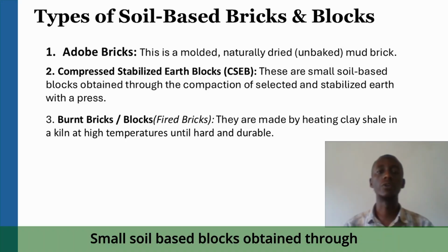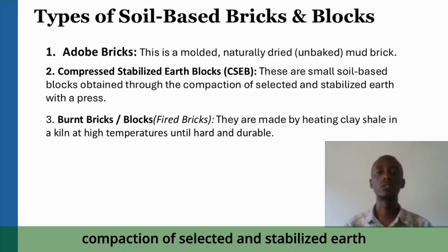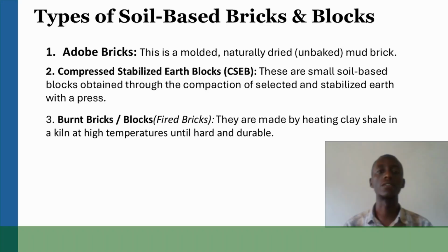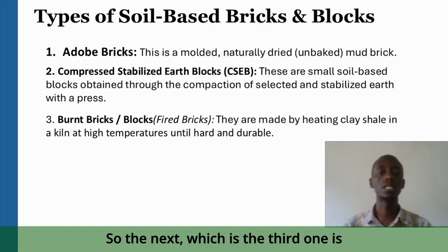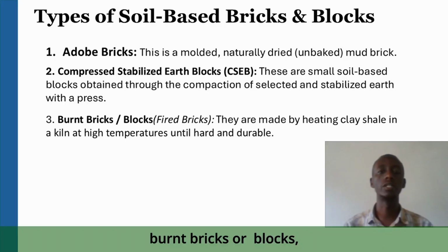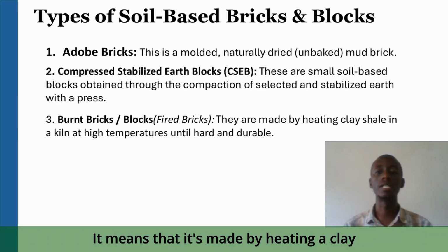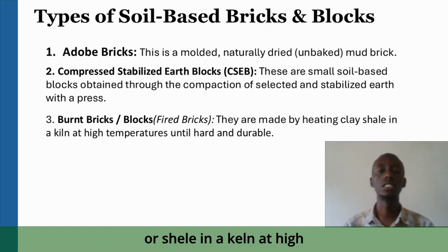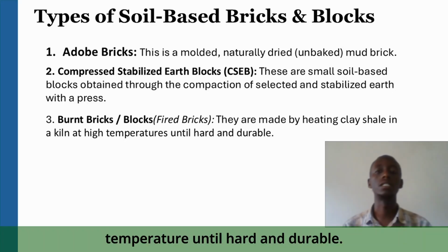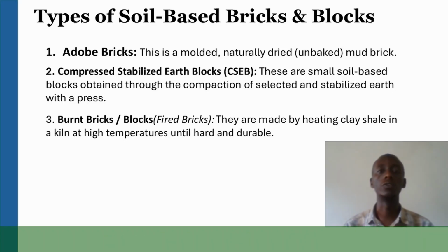Small soil-based blocks obtained through compaction of selected soil into stabilized earth using mechanical presses. The third one is burned bricks or blocks, which means fired bricks. It means they are made by heating clay or shale in a kiln at high temperature until hard and durable.